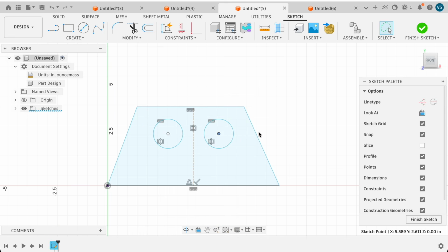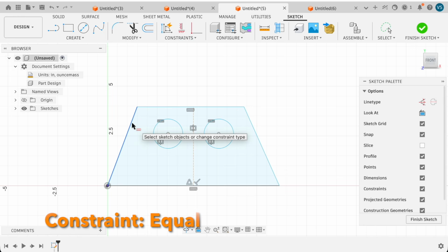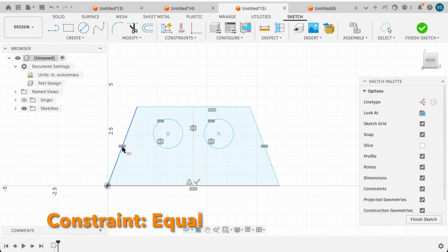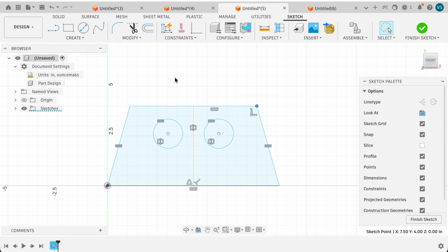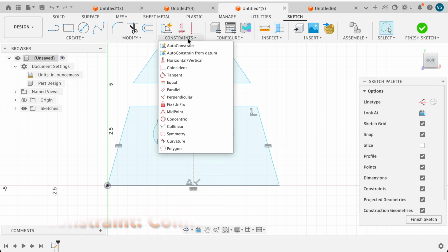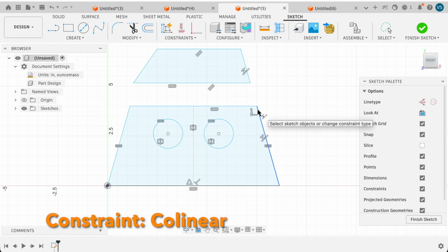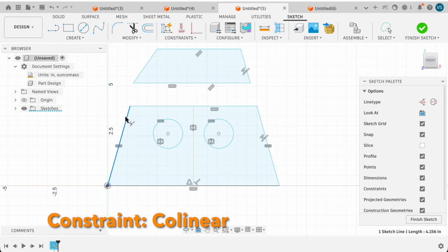So now we can pin them in place with minimal commands. This one and this one here, we're going to make them equal. So this one equals this one. So look, we have the same symbol show up. That was a right click, and we'll hit OK. So now what we can do is we can unlock the collinear constraint here. So just be a quick trapezoid, but then I'm going to constrain the collinears like the parallel, only they share the same trajectory, right?